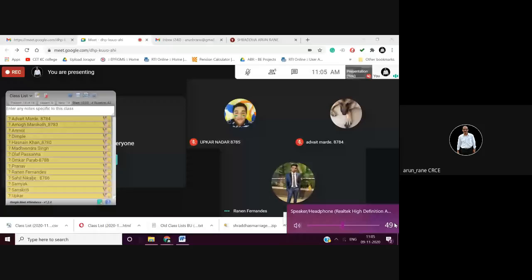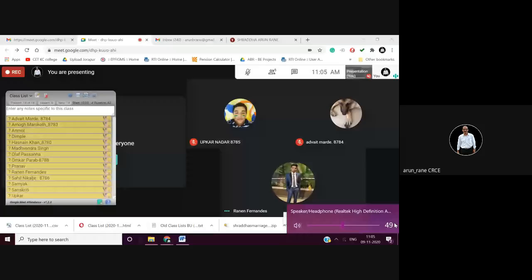Yes, sir. What is C1 and C2? C1 and C2 stand for the corner chamfer. We had used two chamfers here, chamfer 1 and chamfer 2. And R is for the radius. C1 means chamfer of 1 millimeter, C2 means chamfer of 2 millimeter. By default it will take a 45-degree chamfer. If it is a 30-degree chamfer, then you have to use the A angle command.